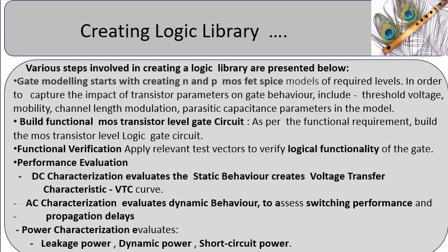Performance evaluation. DC characterization evaluates the static behavior and creates the voltage transfer characteristic, VTC, curve. AC characterization evaluates dynamic behavior to assess switching performance and propagation delays. Power characterization evaluates leakage power, dynamic power, and short circuit power.